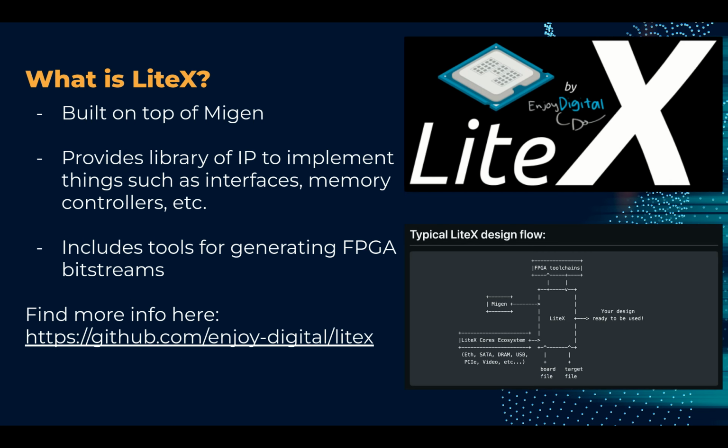Now, what is LiteX? This is another thing built on top of MiGen. It's an open source hardware design platform that allows developers to make their digital circuits with this collection of intellectual property. It was developed by Florent and the M-Labs team as part of the MiGen and MiSoC projects, and it's now maintained by a variety of contributors. It provides a library of pre-built IP cores, and these can be used to implement many functions such as the memory controllers we saw in the previous slide, Ethernet interfaces, UARTs, and so much more.